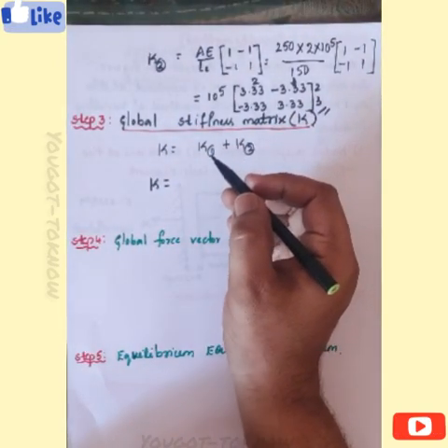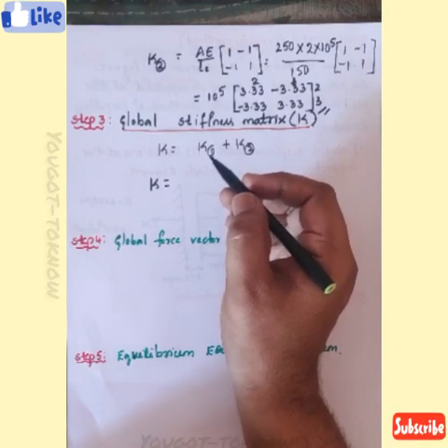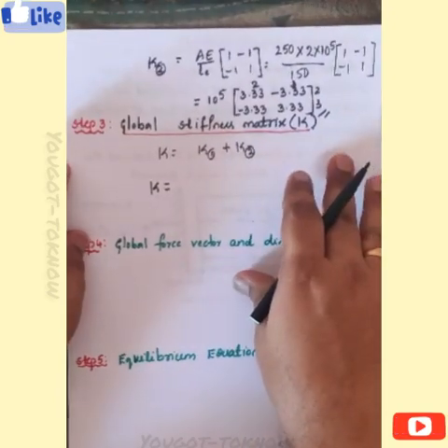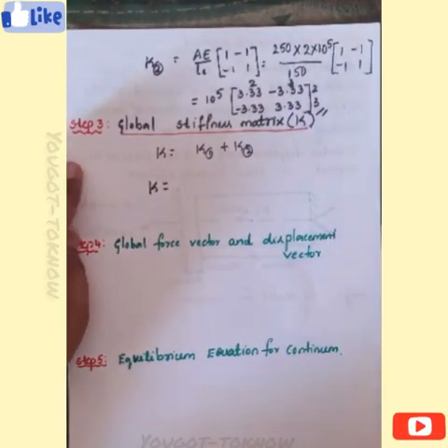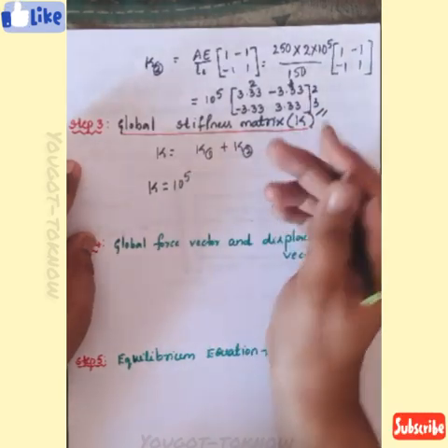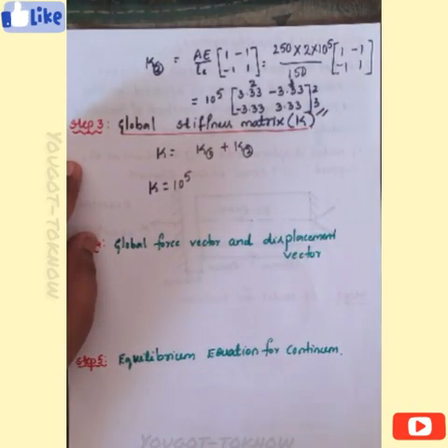The second one also has 2 rows and 2 columns. But if you observe the node numbers, 1, 2, 3 and 1, 2, 3 are there. Also, your continuum consists of 3 nodes, and at each node you are getting one displacement. Because of this, consider the order of the matrix for the continuum. Global stiffness matrix means you are formulating a stiffness matrix for the continuum. FEA model means you are calculating a stiffness matrix for an element.